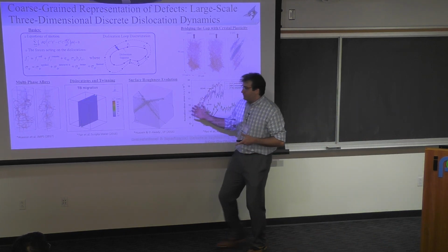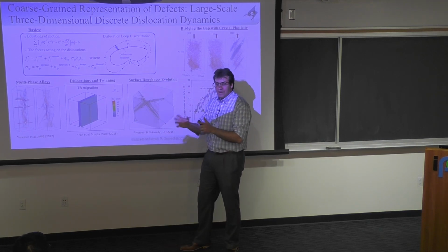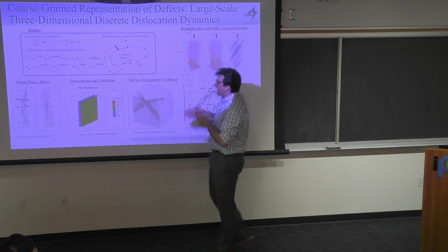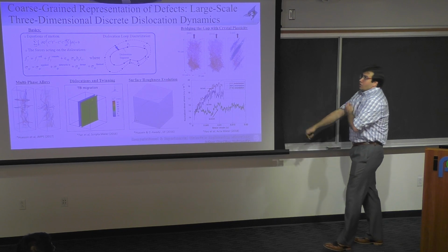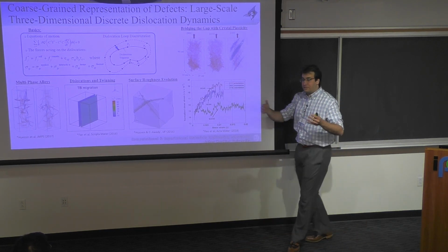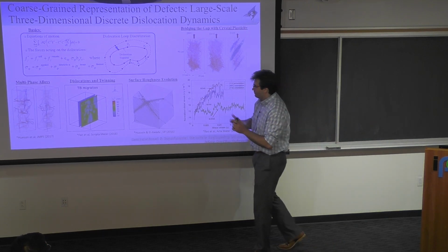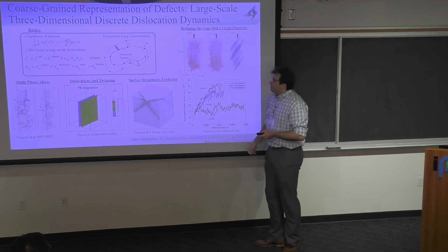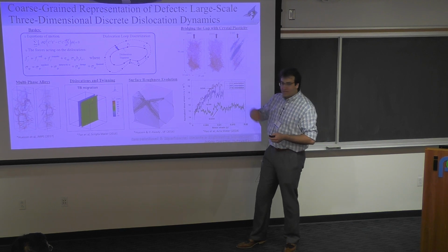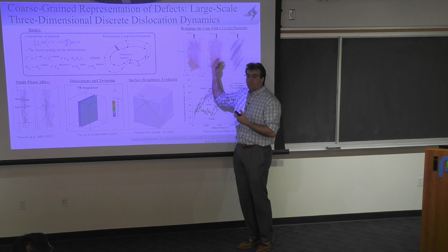Again, a lot of this type of information is really upscaled from MD, but upscaled in terms of physics. I want to identify the physics that relate to the motion of these dislocations and how they react, and we build it into our model. So even though we can do these simulations with a million nodes, multiply by 3 to get 3 million degrees of freedom, that's much less than the trillion degrees of freedom that you get from atomistics. But these simulations are much more computationally expensive because of all the rules that are embedded.